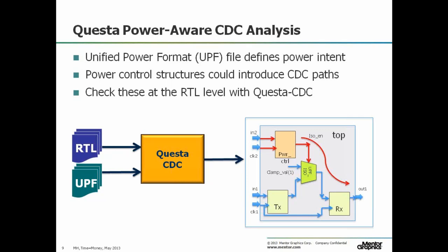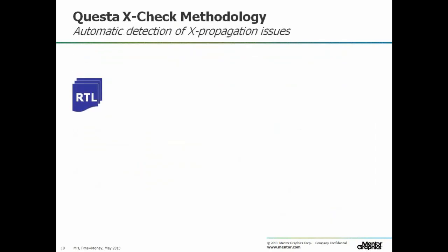So this is just one possible case here, where verifying with CDC may ensure the RTL is correct. When you verify CDC with UPF, we can find additional CDC paths that need to be verified. Another case would be where you have a synchronizer that you may put in place, but it may span a power domain, in which case isolation could quite easily be placed right in the middle of your synchronization path, which is obviously a bad idea. So combining technologies here, both used in formal to do some further analysis.